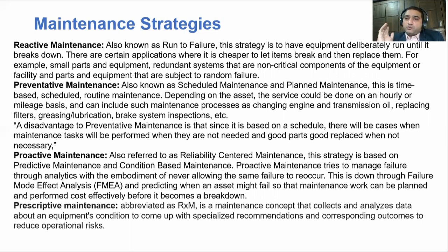Okay, like suppose you are maintaining a lift in your organization. You can actually have some sensors that will measure the actual wear and tear of your rope, or the actual number of runs or travels of your lift. It can monitor with vision sensors the actual wear and tear of your bearings and some critical parts, and then it can do the failure mode analysis, and then it can communicate that now it is time to replace the rope, it is time to replace the pulley. So that kind of communication can be planned with the proactive maintenance.